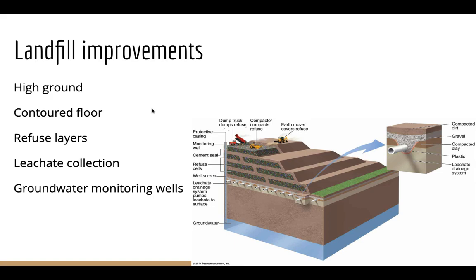Clay not only is relatively impermeable to water, so that leachate won't be able to get out of the clay and into the groundwater, but it can also retain positively charged ions like metals, like we talked about with CEC. That contoured floor will also often have a plastic liner and at least 2 feet of compacted soil, which will just additionally buffer anything that might be trying to get through the bottom of the landfill.